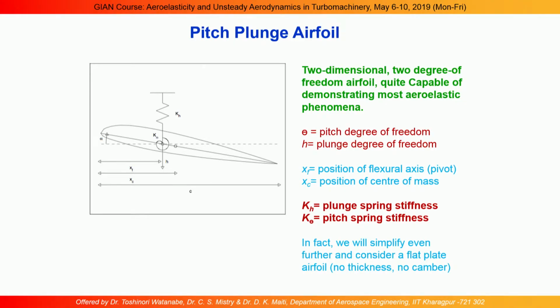See here, in static aeroelasticity I considered only the torsional stiffness, meaning the torsional equilibrium equation. The torsional equilibrium equation is not coupled with the bending equilibrium equation, whereas the bending equation is coupled with the torsional one.